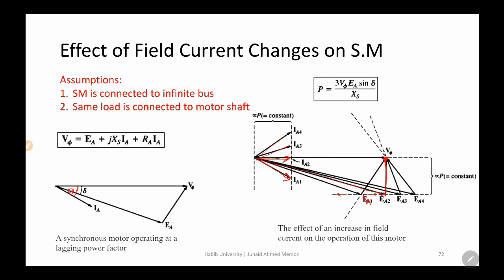So still, what's the importance of this? Now you have a motor. Motors are usually inductive loads, right? As you might have recalled from other courses, motors are usually RL loads. But we now have a kind of motor, the synchronous motor, which can behave like an inductive load, which can also behave like a unity power factor load, which is a resistive load. And not only that, it can also behave like a leading power factor load, like a capacitive load, and that is very strange. So it means that we can not only correct the power factor when operating the synchronous motor, but we can also use the synchronous motor as a device to correct the power factor for your system.